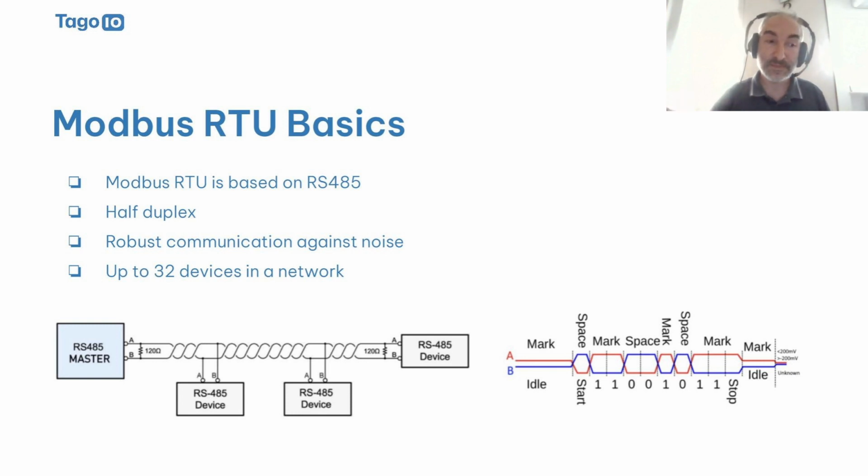So from my side, I can tell you that Modbus RS485 is a very robust protocol and adapted to industrial environments. And with our devices, you can make any industrial Modbus RTU compliant slave a wireless device, because with our Modbus to LoRaWAN interface, you can add LoRaWAN connectivity to any industrial Modbus slave.